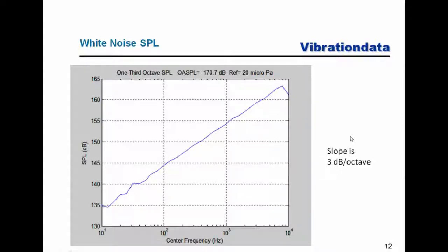Now previously we had also looked at pink noise, and if we were to synthesize a pink noise time history, take its sound pressure level, then the pink noise would have a flat sound pressure level at some constant dB level. And maybe you can do that as a homework exercise. Okay, so let's see what else.